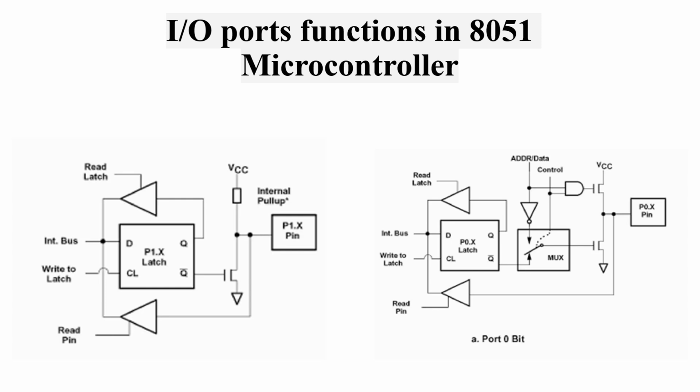In port 1, you can see it is strictly an input output port, which is used for any general purpose application. It does not have any alternate function like sharing the data bus duties. Often it is used for interfacing simple buttons, LEDs, or other digital displays, which act as dedicated input-output devices. Yes, so now you are clear with port 0 and port 1.